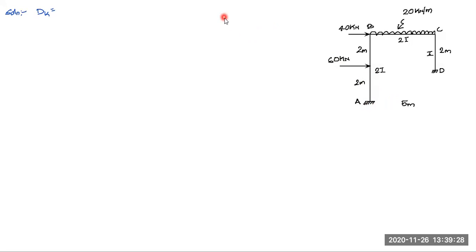Here you can go with the formula: each joint has 3 possible displacements, so 3j, minus the supports, where displacements are restrained by the reactions. If I provide a hinge support, it will restrain the two translations in x and y, and allow rotation.